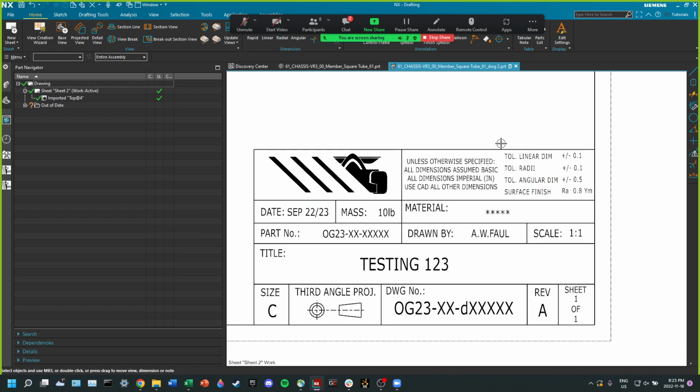One thing for all of our parts is we sort of have to think about tolerances and our manufacturability. So these are just standard ones that I've pulled from Multimatic. But these tolerances obviously aren't necessarily obtainable for certain parts, and I think they're in metric still. So when you're doing your drawing, make sure you update the tolerances. And if you have questions about what tolerance we could achieve on a certain part, talk to Kieran or myself, and we can figure out what sort of tolerance you should put on something.